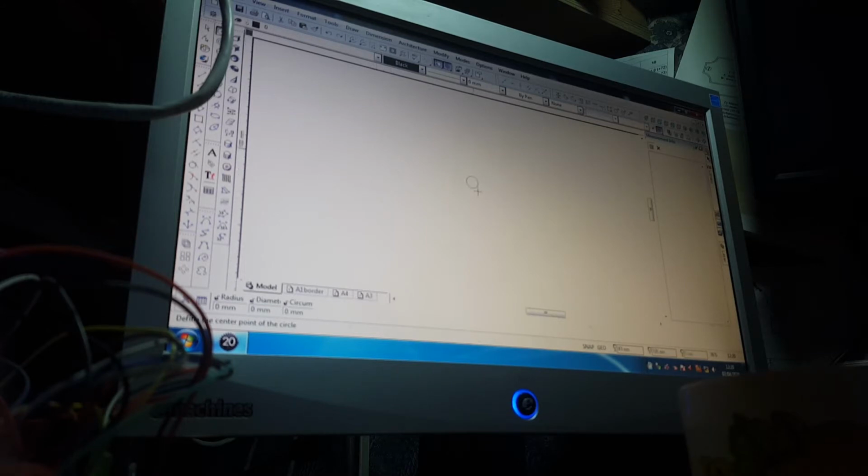Okay, so select that tool, and then I go down to my menu tool and go linear copy. X step, so in the positive sense, let's go 25, in the Y sense 0, but 10 sets, enter. So we've got multiple copies of the circle tool.